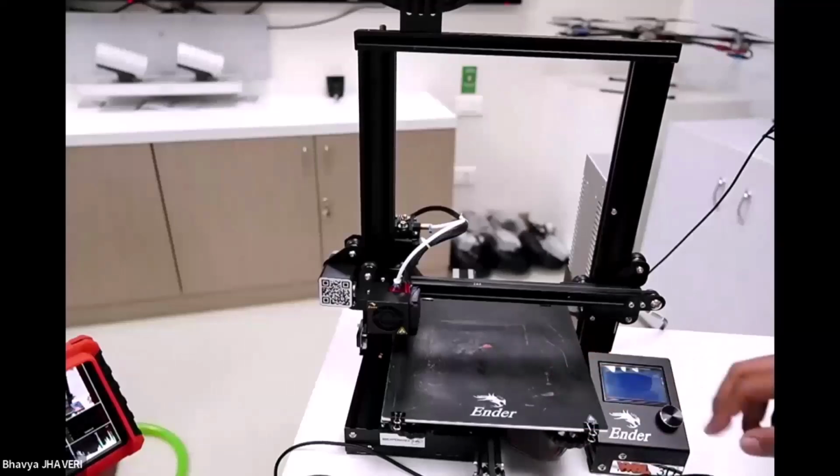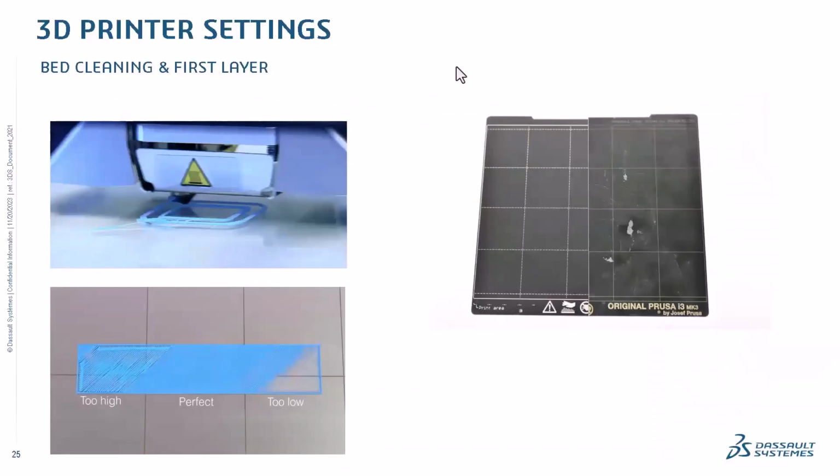And finally, printing of the first layer, as you can see in the slide. The very first layer that gets printed is very important. The first layer has to be perfectly stuck on the bed, and therefore the bed cleaning is also very important. This first layer that gets printed will ensure whether you have leveled your bed correctly and whether your bed is cleaned correctly. If the bed is not leveled, then as you can see in the image, the first layer will not get printed properly.